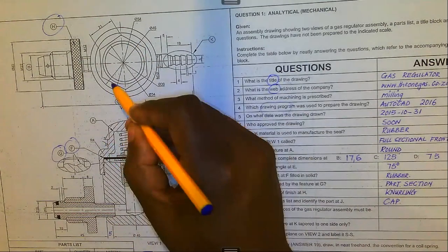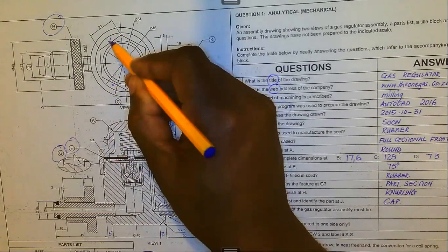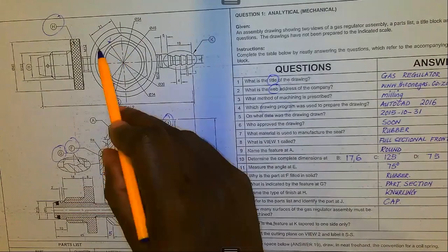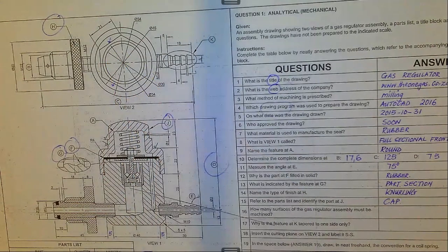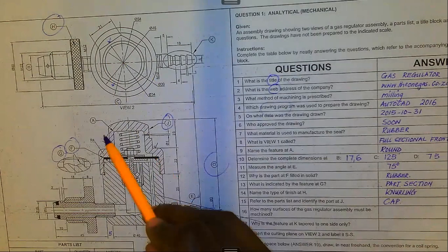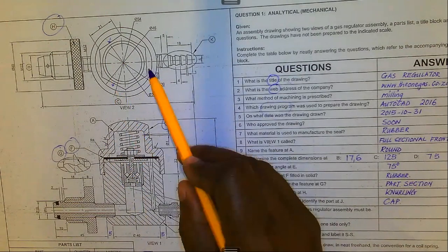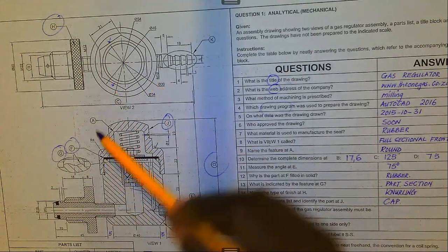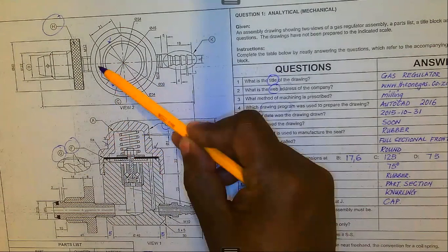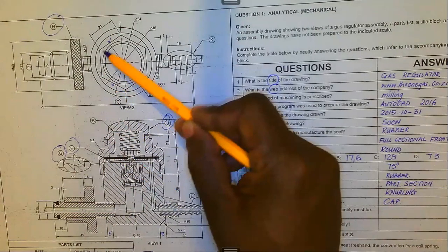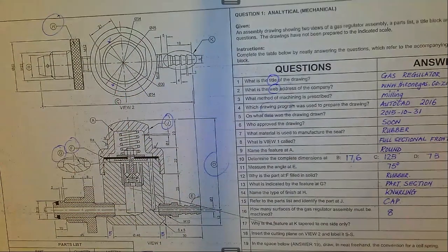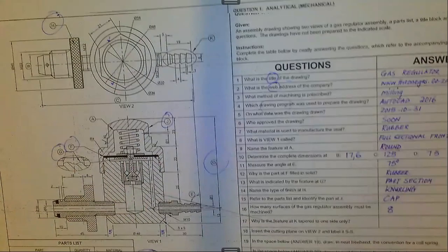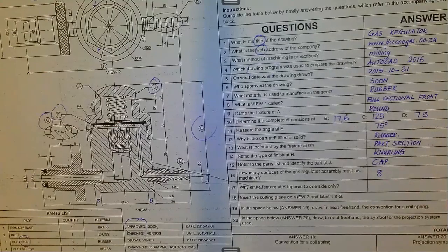There is another one here, and another one there. If this surface is machined, the understanding is that this also, that also, and this one, and that one, and that one, they all need to be machined as well. So we've got 1, 2, 3, 4, 5, 6, 7, and 8. This one is already defined, so we have 3 plus 5 more, which gets 8. So we write here 8. Sometimes you need to think outside the box and look at the bigger picture in terms of the question that has been posed so that you come up with the correct answer.